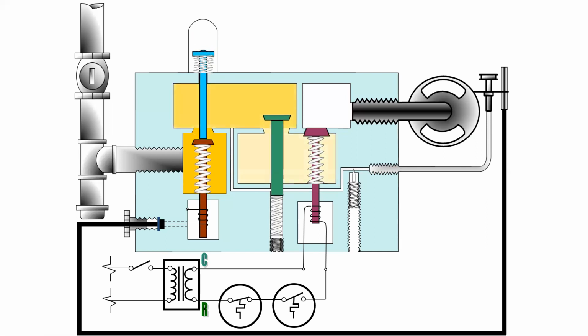And in doing that, we've allowed gas into this main chamber as well as this small line that supplies the pilot burner. At this point, while we're holding it down, we're going to take a match and we're going to light the pilot burner.